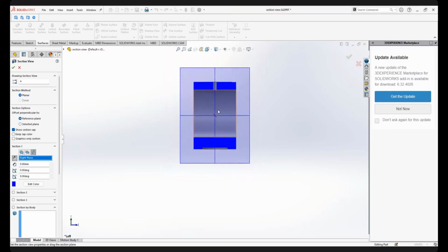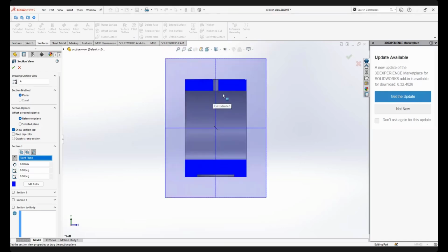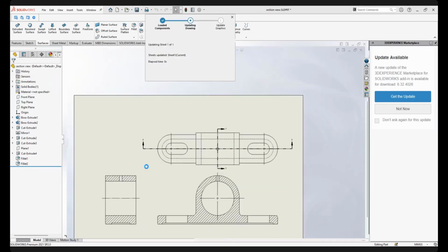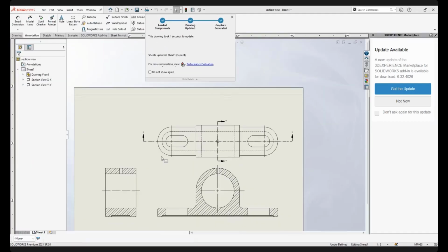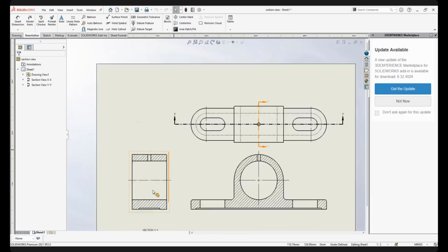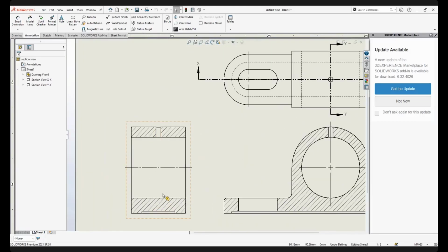But we don't do the right view here, the left view here on this side, the plan view. We bring the 45-degree line, right? That's why in your drawing, your answer is like this. You bring the 45 degree. Okay, this is 45 degrees. So this is your section YY. This is your 45 degree line. So your answer is like this. So it's how it looks like.